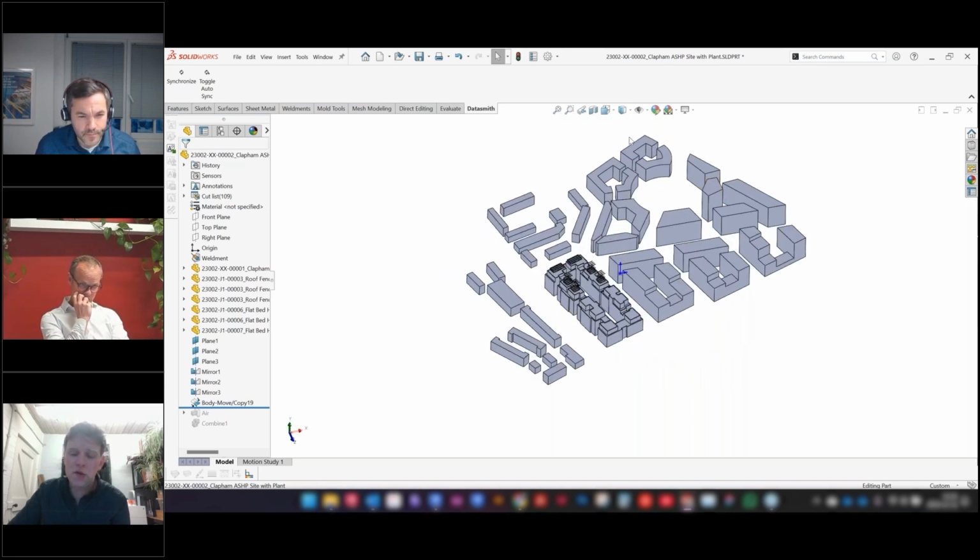We use SolidWorks for the geometric modeling for two reasons. One, because we're good at it, but also secondly, because there's actually an API plugin for SimScale and SolidWorks, which means that when I create my geometry in SolidWorks, I can, with a click of a few buttons, push it to the online SimScale platform. So that's really helpful when it comes to the iterations that we're making.